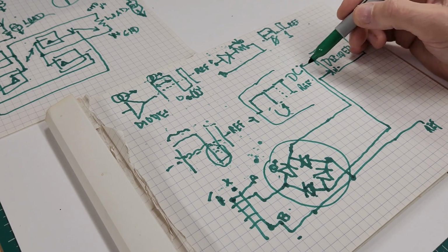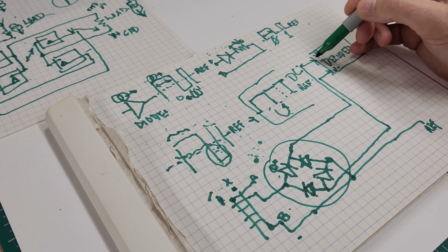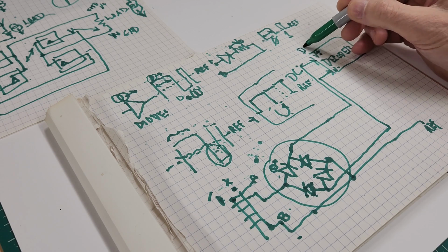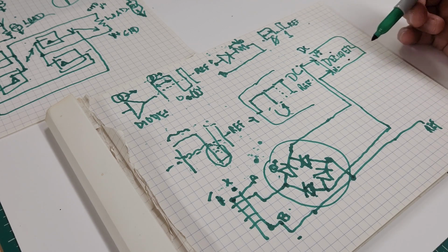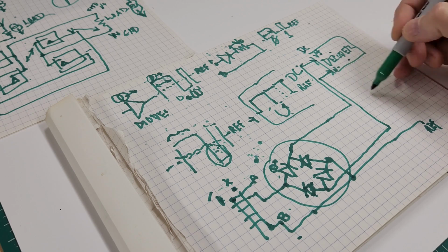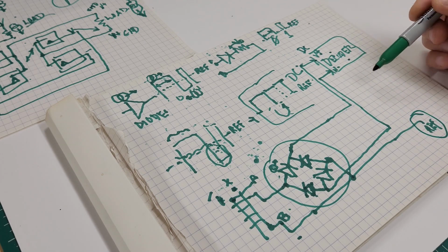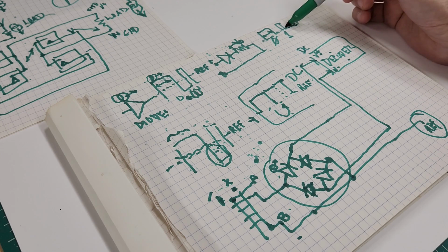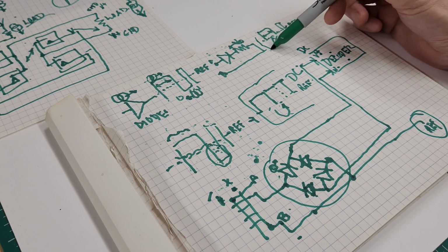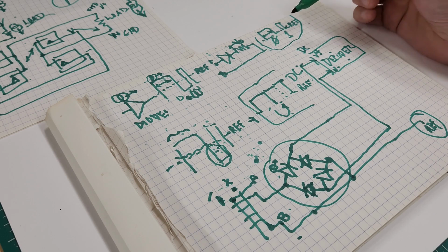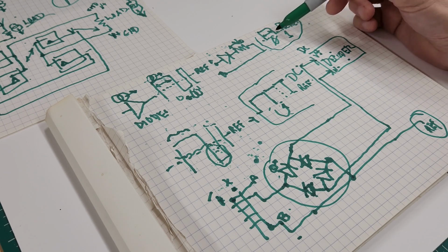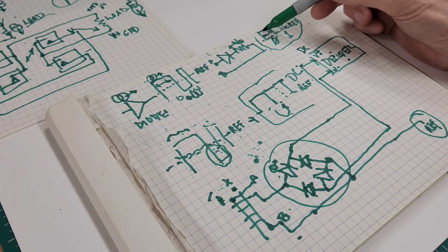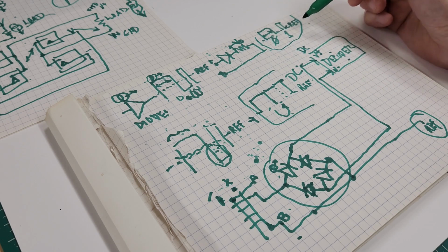But at any rate, this crude circuit demonstrates that there's a DC voltage applied to the decoder, and that DC has a reference voltage. And that reference voltage is the same reference voltage that we were saying is used by the decoder to be able to see these step waves and extract those durations.